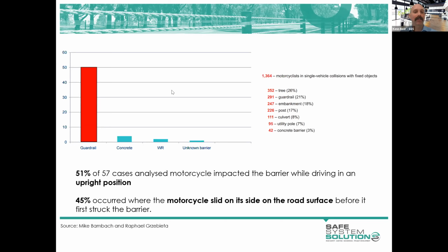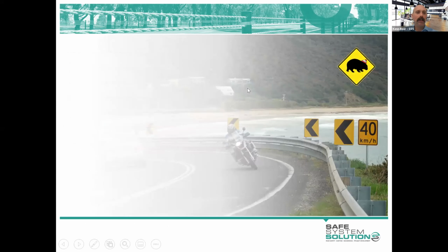It's the most out there, and there are the minimum length requirements, which Jamie touched on, and wire rope's very significant there. So it's really used on those long, straight-ish roads where fatigue is the issue and people are leaving the road, falling asleep and the like, and motorcyclists aren't tending to do that as well. So quite a number of things in there.